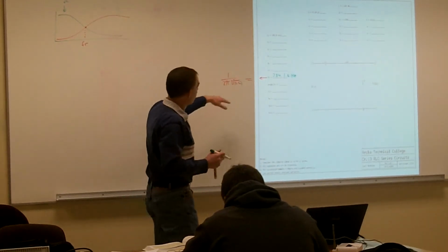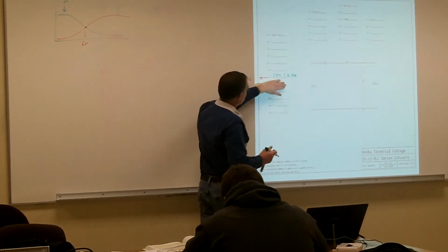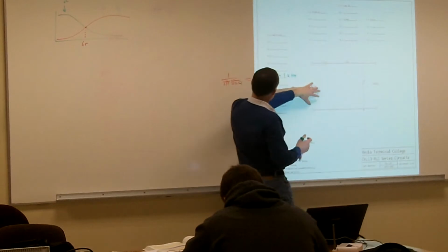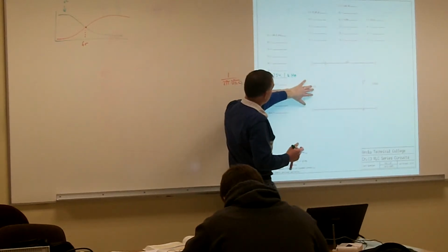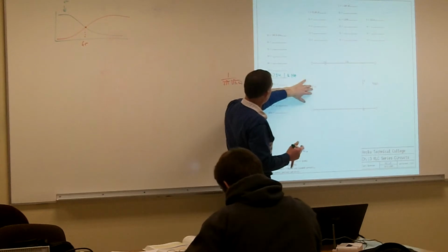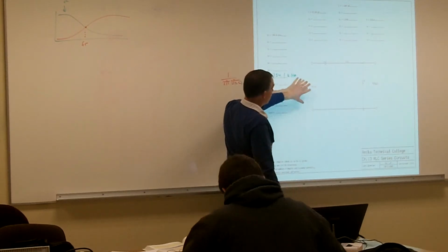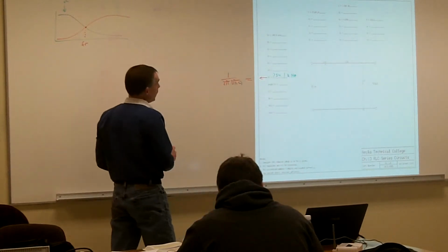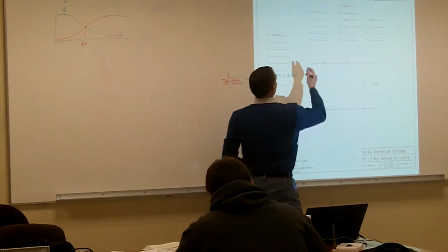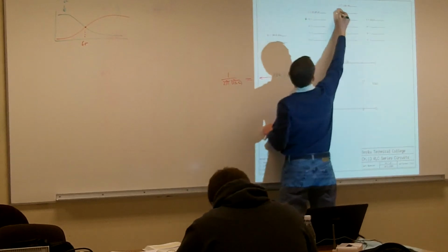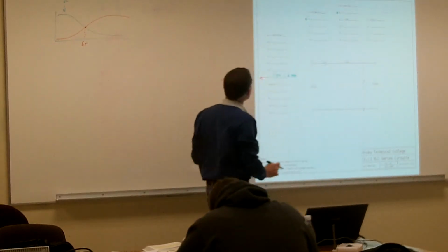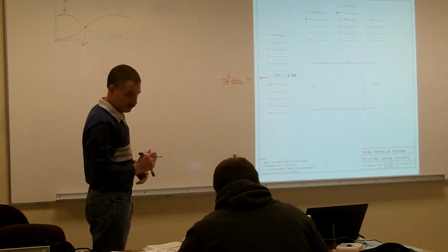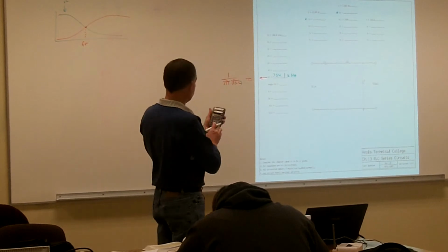All right. So now once we have our frequency, this circuit is going to be tuned to filter out all the frequencies except for the 734.1 kilohertz. That's the frequency that's going to be coming out of our output. Once we have that frequency, we can calculate out what our X of C is and our X of L is, because now that we know our frequency, we can go ahead and calculate X of C and X of L.